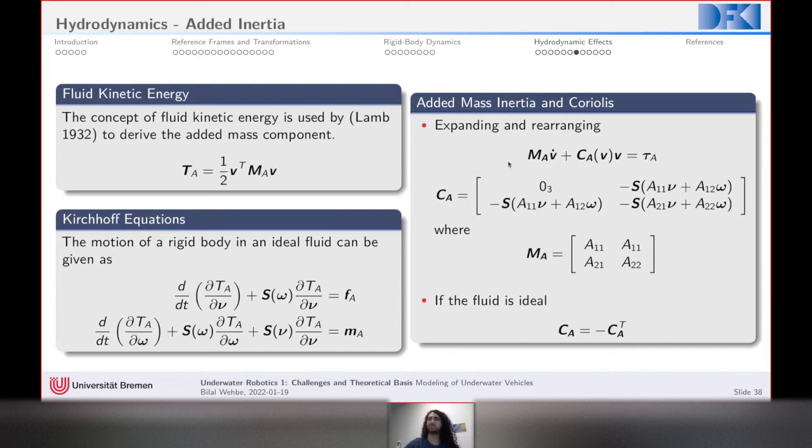Depending on the geometry of the body, this added matrix can be as if we are virtually trying to accelerate double the inertia, as if we are doubling the actual inertia of the vehicle when it's moving in air, if we put it under the water.